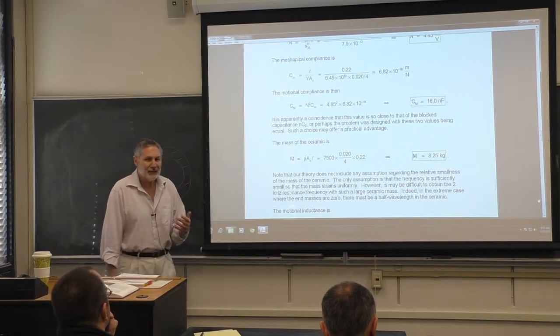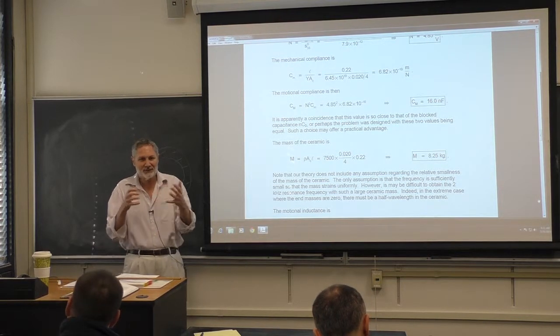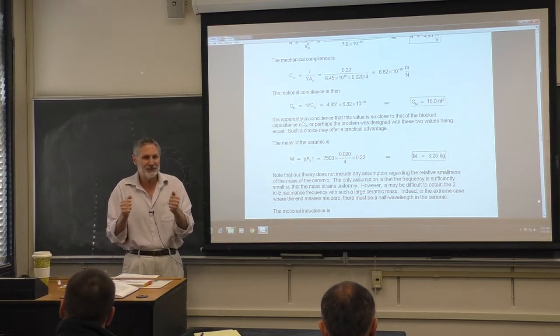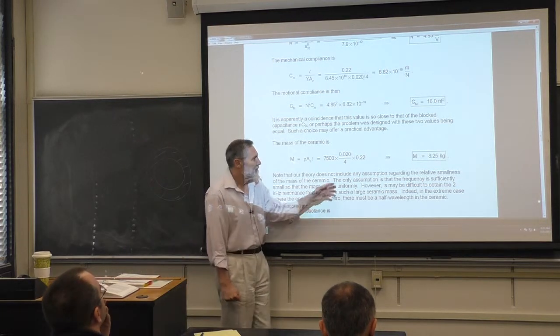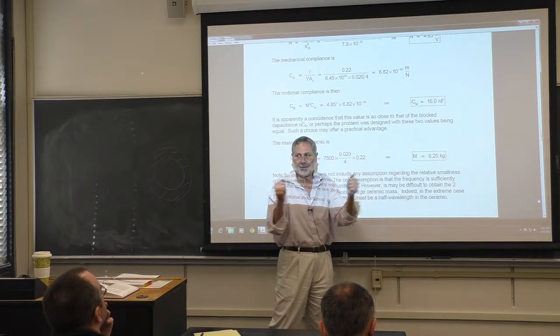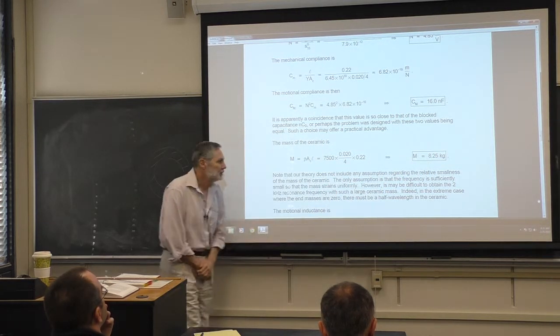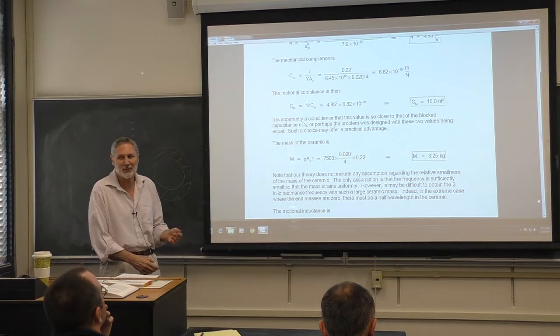However, how do you get the 2 kilohertz resonance frequency? This certainly involves the ceramic, not just the stiffness, but the inertia. So you may have trouble, since this is comparable to, even exceeds, each of those masses, the 5 kilograms. You may have trouble coming up with the 2 kilohertz. See, that's not in this problem, coming up with the 2 kilohertz resonant frequency, right?